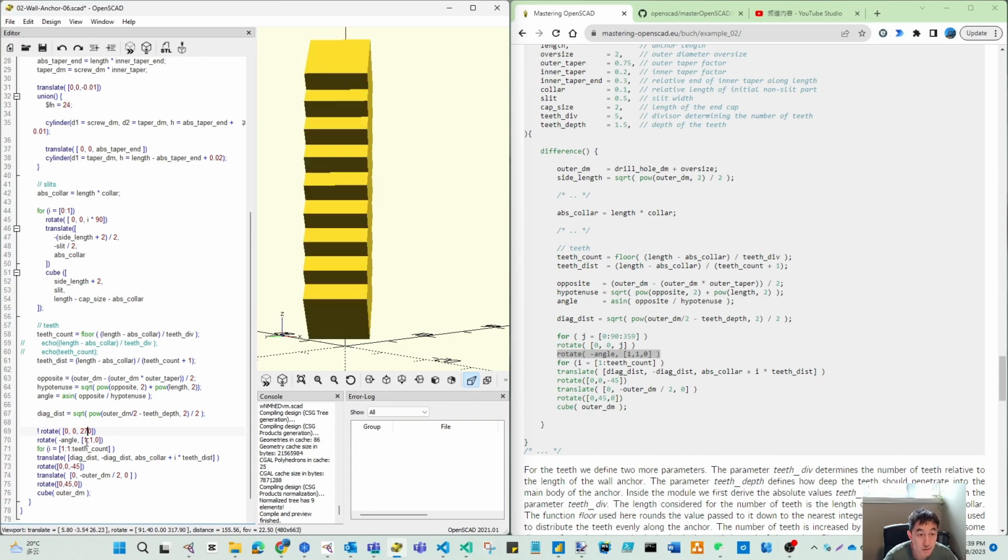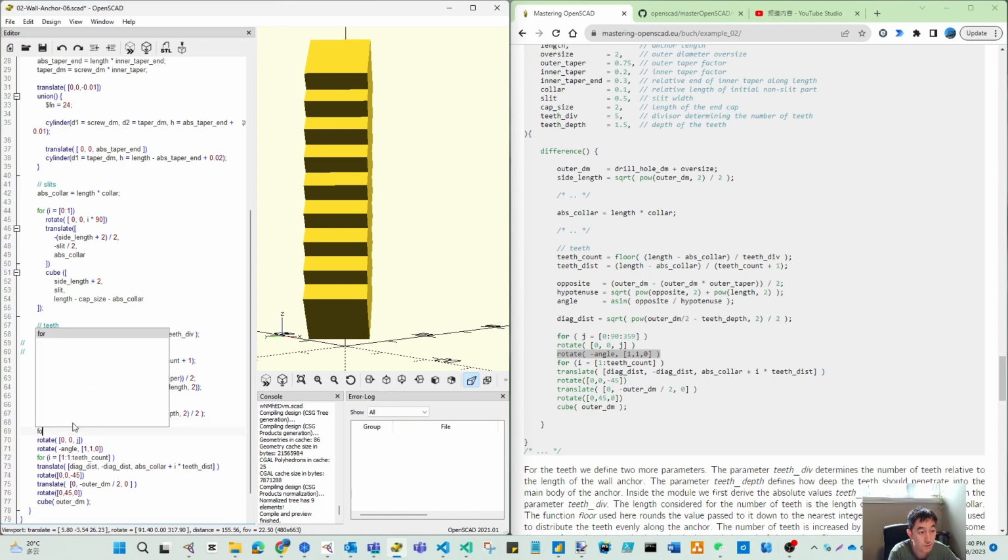270 is come to here. So that's the reason we need to have this 4 altogether. So we define our J, and then the 4J equal to the degree. So step is 90 degree. You should not have a 360. You should have 359, so that is not overlapping.